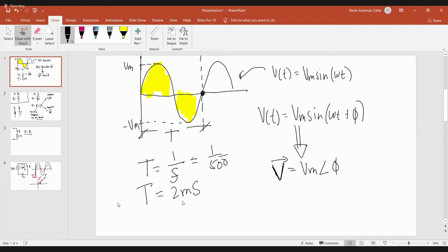So you start saving at 2 milliseconds and then stop saving at exactly 6 milliseconds. So that is, you are now recording 2 more periods in your analysis in LTspice. So that's it. Do you have any questions, guys? Clarifications? Violent reactions? So none.